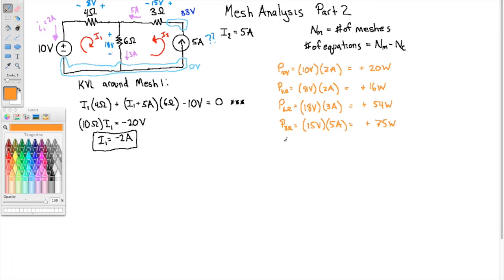Now, how about the current source? The power in the current source. Well, there are 5 amps through it, 33 volts across it. So 33 volts, 5 amps through it. And so that is, what, 165, I think? Alright, and notice here the current is going from low potential to high potential. So that's the marble going up the ramp. So that's an active element, meaning it's supplying power.